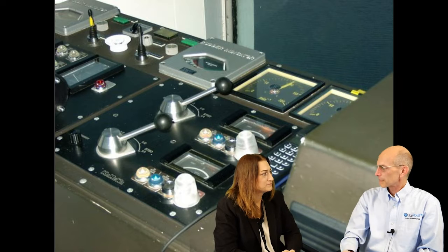I don't know that, but my guess is the reason they put the cups there is somebody kept pushing the button by accident. Well, then that's a poorly designed control. If the human keeps accidentally pushing things, then it needs to be designed so you can't accidentally push it. Now, this is a good initial thought, but we probably need something a little more permanent, like a spring-loaded cover or something like that. Okay. So nothing wrong with covers. That's okay. Just not Dixie cups. That's probably not the right answer.